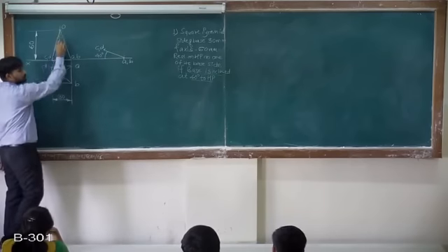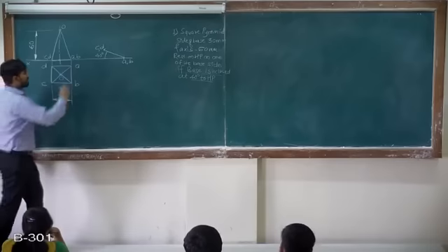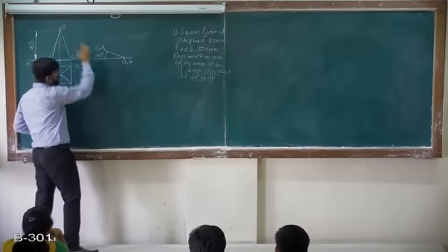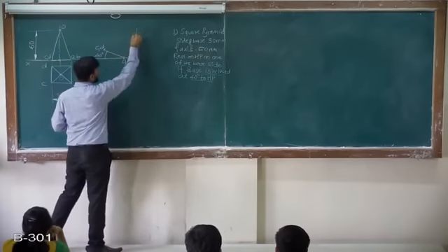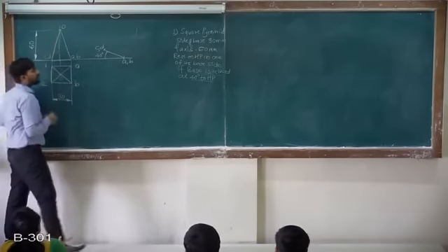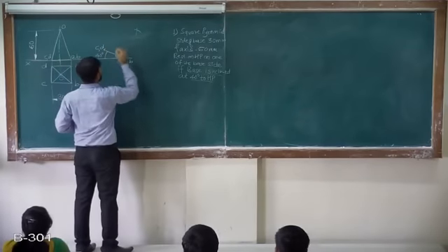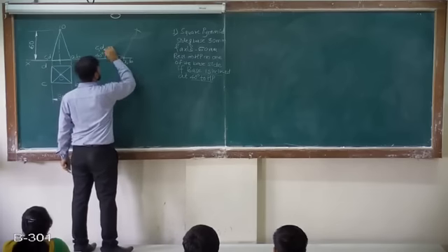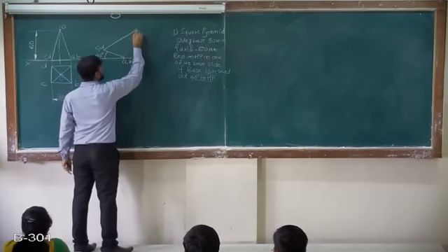Similarly, we need to take this point O from this view. So take a distance AB to O, mark one arc from AB. Same, take a distance CD to O, mark from C. Join it.